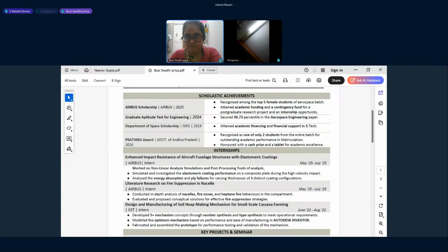Okay, sir. So in propulsion, if you are talking about high temperature, the turbine blade is the one which is at the highest temperature. Then the cooling methods, as I told you: inside the hollow, cold air is passed through, and externally there are paints applied which will cool down the turbine blade. And turbine blades are made from single crystal castings to withstand such high temperatures.